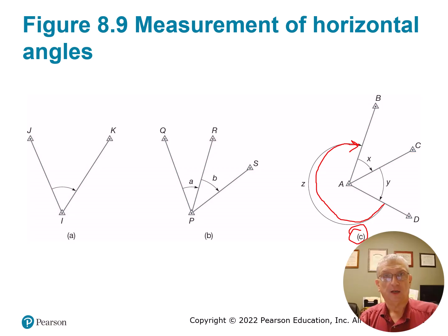Well, you would use that lock plate and that tangent screw to get back on your backsight with your 30 degree angle. Just say it's 30 degrees, 0 minutes, 00 seconds. Then you would unlock your top motion again, lock it down, dial it in. Let's say you come up with 60 degrees, 00 minutes, 4 seconds. Well, the average of that would be, if you take the total doubled angle and divide it by 2, 30 degrees and 2 seconds.